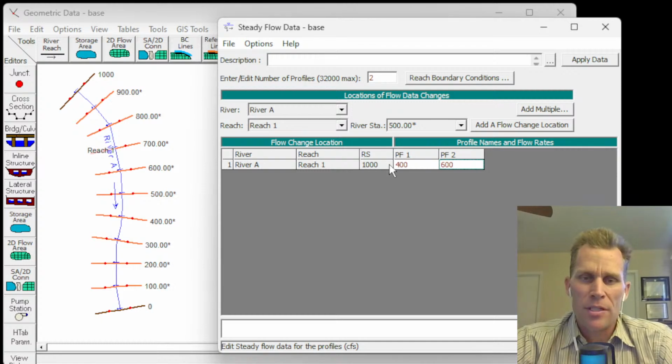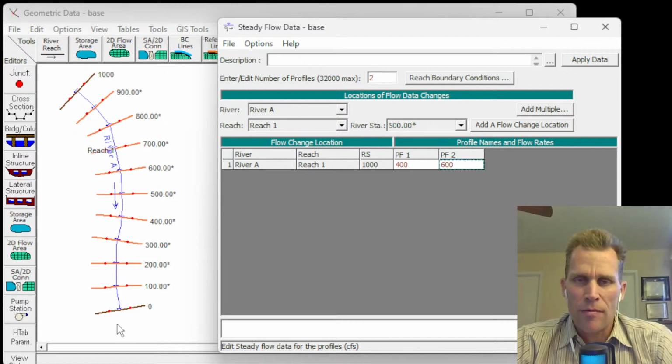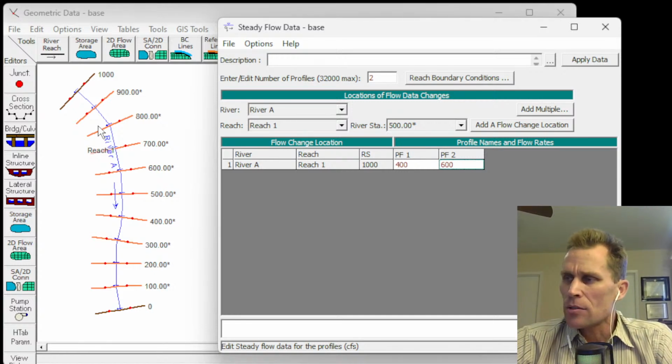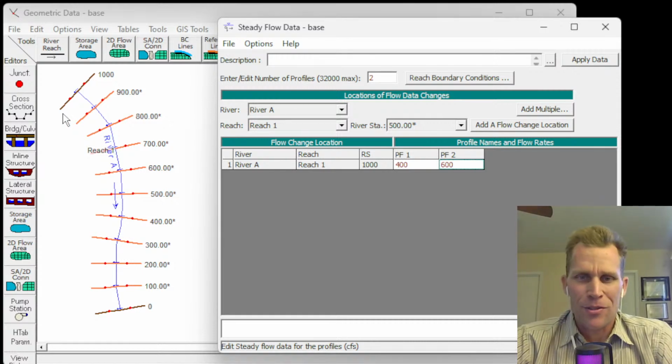So for instance, look at that previous example where I had, say, 100 CFS coming in, and then it increased to 150 CFS, and then it decreased down to 75 CFS. Then, yeah, because there's more flow, you're going to have higher flow rates, of course. That's what we're specifying. But we're also going to have a higher water surface elevation, higher energy, higher energy grade line, probably a higher depth of water. The velocity would probably be higher, at least in certain spots. The velocity profile within the reach is kind of tricky; I'd have to actually map it out. But I would say that the maximum velocity at any single point would probably be higher with the higher flow rate. Does the current change? Yeah, when you said current, I believe you meant flow rate. So hopefully that answers your question. If not, just keep on typing and I'll just keep talking.